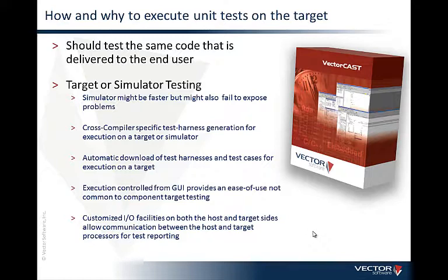It might make for faster test case execution. But our simulator might have some kind of defect in it, or the simulator might be correct in some way that the actual target has some kind of defect. So it's possible to execute all our test cases on the simulator and not expose problems.